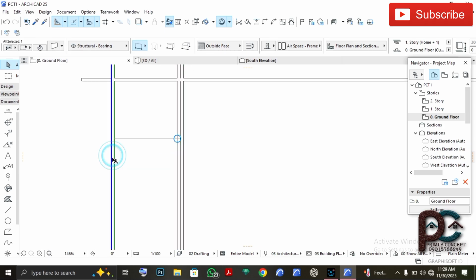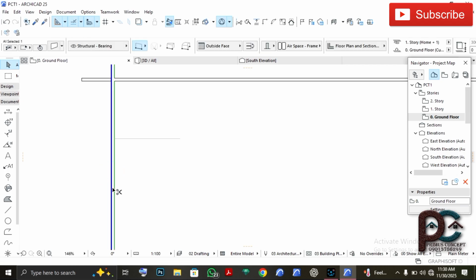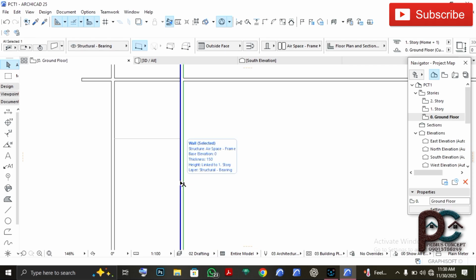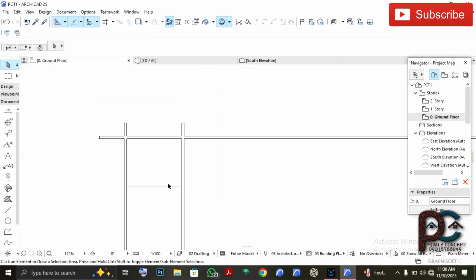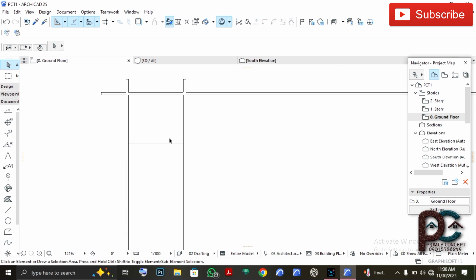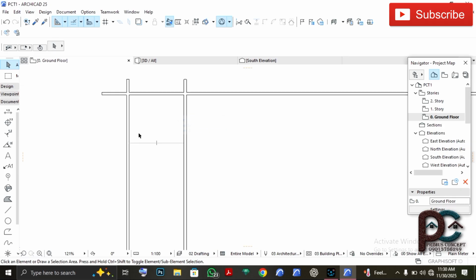If I want to shift this, let me delete this too. If I want to shift this now, I'll do Ctrl+Shift+D to drag a copy, and then I can just equally press 3,450, and that is it. It's exactly at that point I want. So that is it for you. Any way that you find easy, any way you find compatible, you can actually go with that. That is the width of my room.